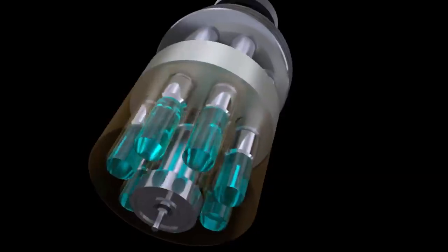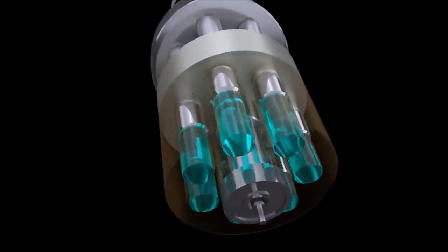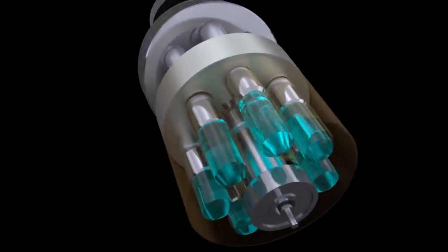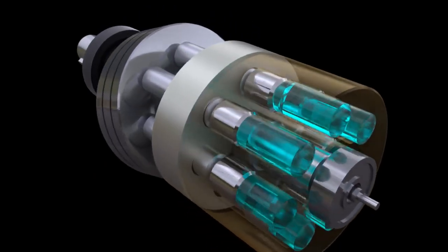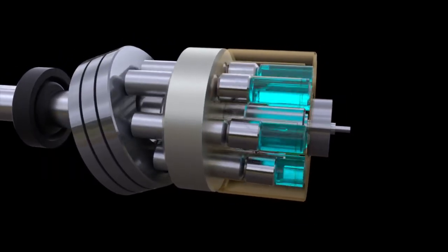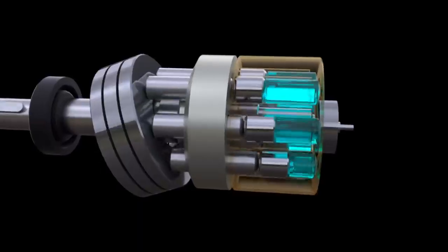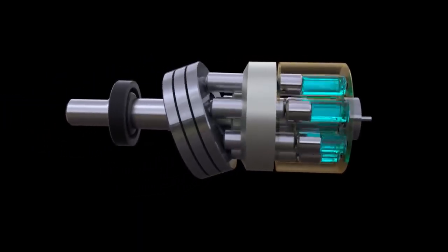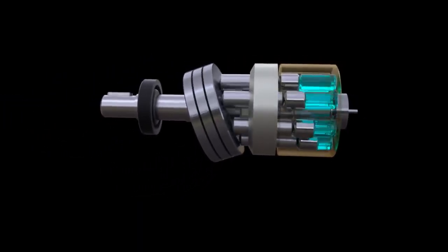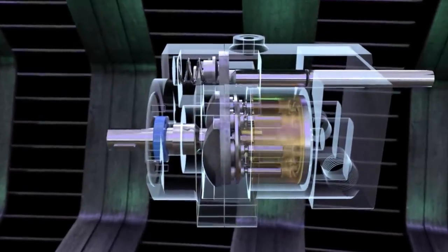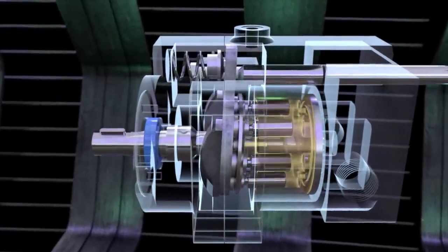to the discharge channel. The pumping capacity of an axial piston pump is determined by the number and diameter of its pistons, the space between them in the block, as well as their stroke. The stroke of the pistons is determined by the angle of inclination of the bent axis, or the swash plate. The longer the stroke, the greater the pumping capacity. By changing the angle of inclination of the swash plate, you can influence the stroke, thus regulating the pumping capacity.